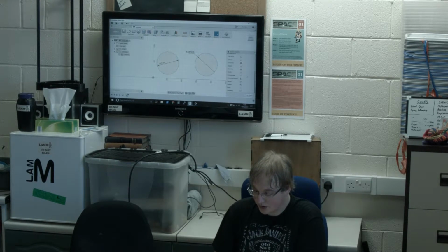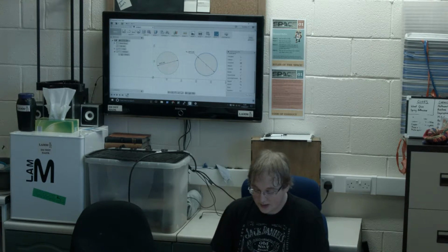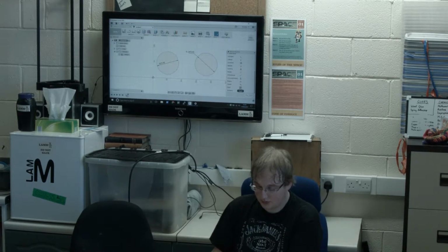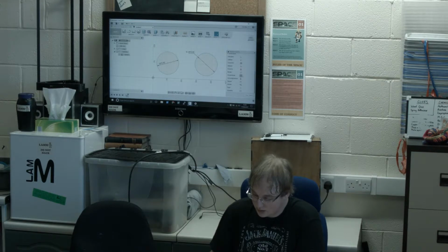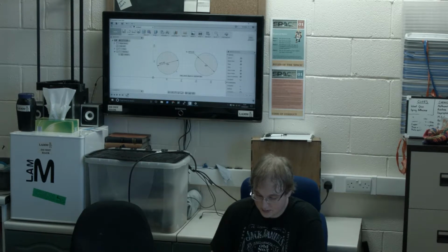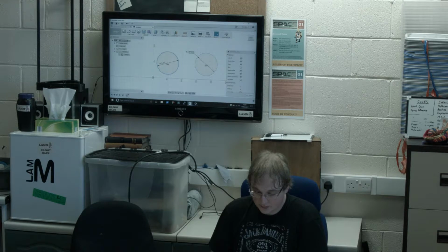And if you're unsure which ones you can use, you've got all these, like symmetry, equal size, smooth joins, tangents, and concentric ones, so you can make circles within circles quite easily. What we need is, I think, the horizontal vertical one. So you click the constraint you want, click the first one, click the second one, and that should be it. Now if we move that one, I've not constrained it horizontally, but now they will always be horizontally linked.